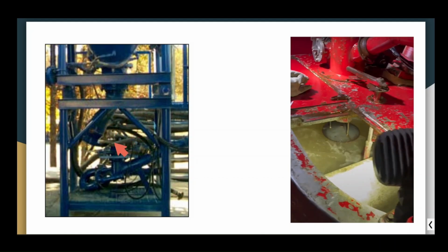There is a special sack, a special hopper. It is attached by hammer union, connected to the knife gate. The knife gate is located here, and cement drops, cement inlets here right to the knife gate. Your water supply line is here as well. This special hose is also attached by hammer union to this low pressure line in order to mix our cement slurry.